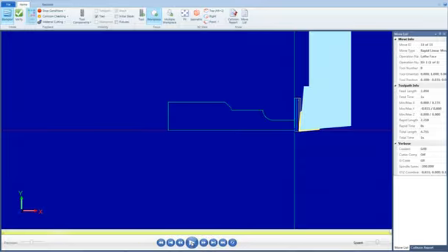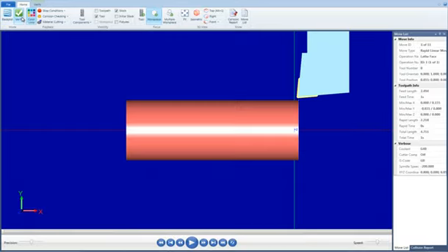Next, we will simulate the toolpath and verify. From the Mastercam Backplot Home, select the Verify button. Verify mode shows the path the tools take to cut the part with material removal. This display lets you spot errors in the program before you machine the part. As you verify toolpaths, Mastercam displays additional information such as the X, Y, and Z coordinates, the path length, the minimum and maximum coordinates, and the cycle time. It also shows any collisions between the workpiece and the tool.